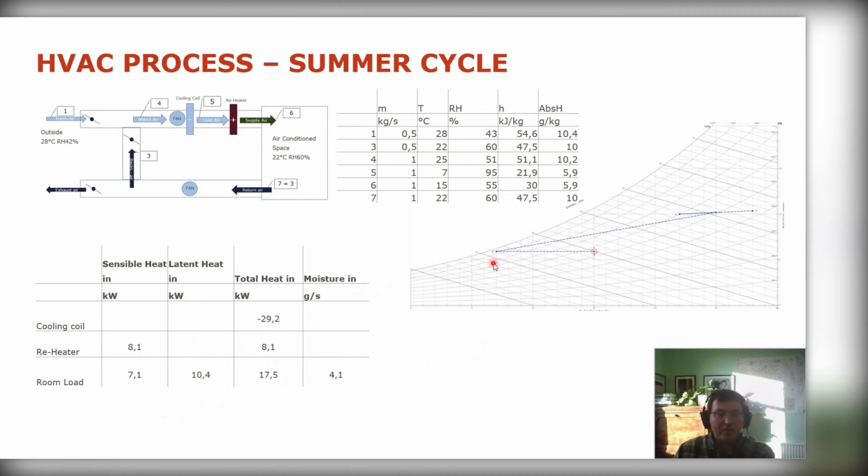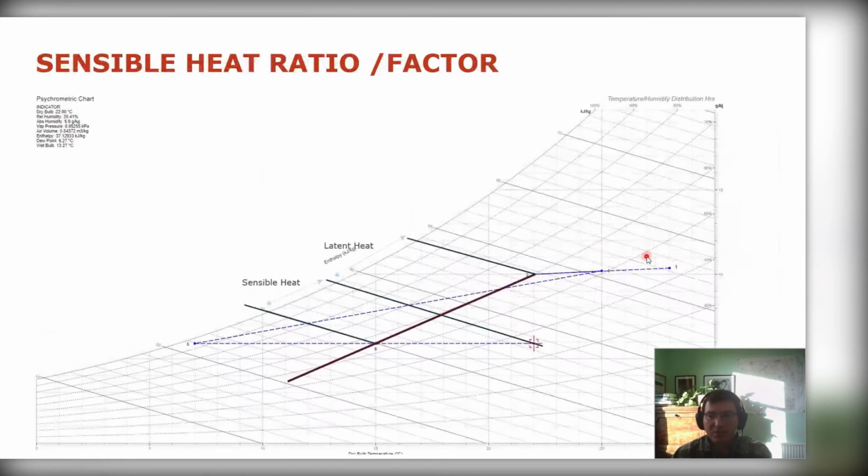dry air, or as much dry air, so you will not be absorbing as much moisture from the air. Therefore, as I said before, the relative humidity would be climbing up and up and up in the room. So what we're achieving here is a perfect combination where we're providing just enough cooling and just enough drying to the room to keep it at the conditions that we need. And that's the important thing. So that's where the sensible heat ratio comes in.